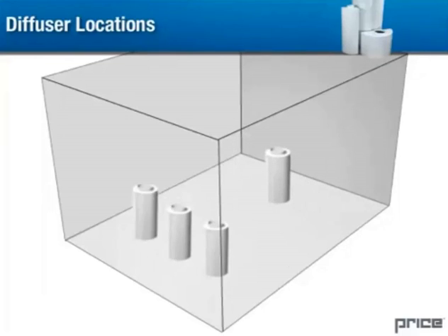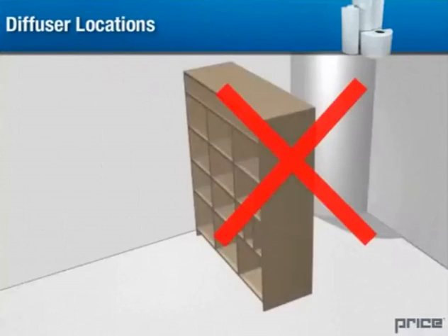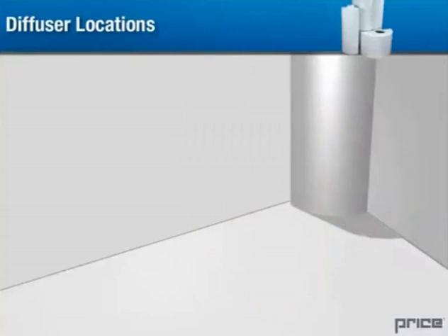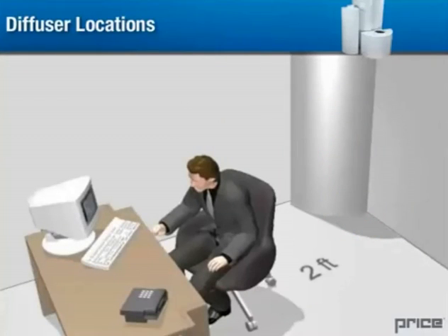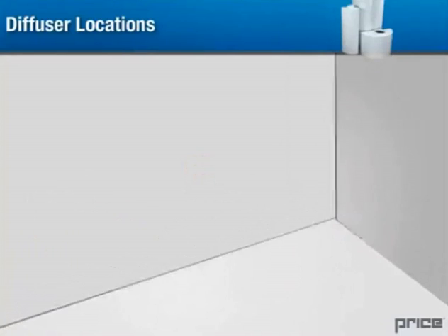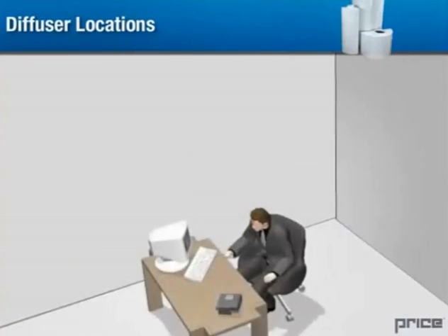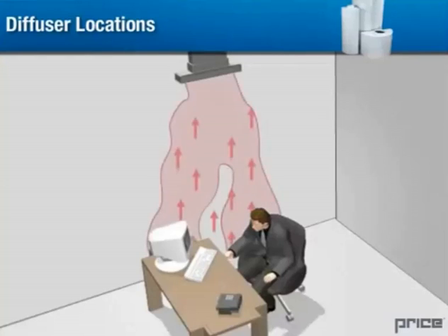Place more diffusers in areas which have a higher cooling load. Avoid placing large obstacles near the diffuser face. Place diffusers no closer than 2 feet from the occupants. For the air return outlets, it's essential that they be placed at high levels, either on the wall or in the ceiling. The same model types for mixing systems would apply to displacement systems. Locating the return air outlets above strong heat sources will ensure the efficient removal of the heat and contaminants generated by the thermal plume.